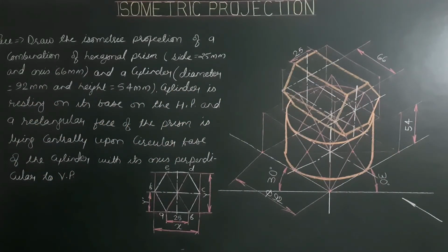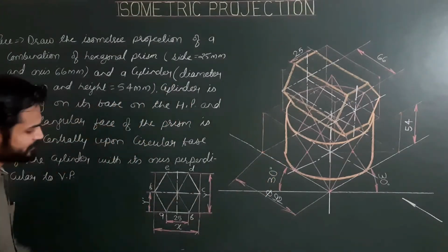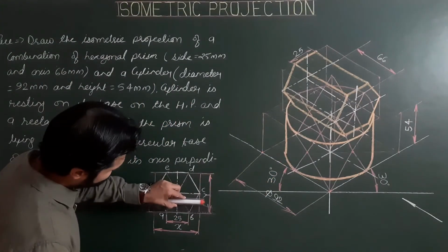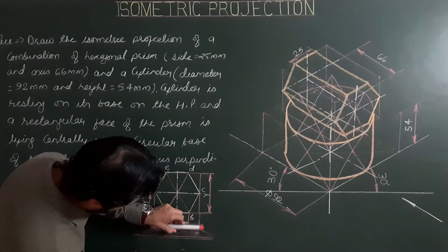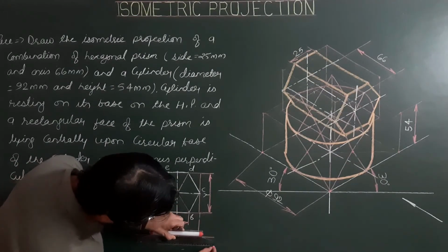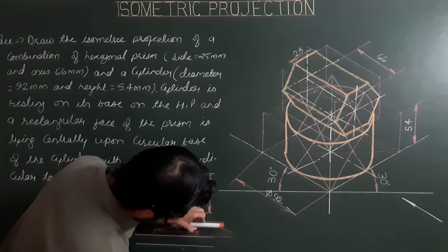And last, naming of the helping figure and final answer. So please write these headings in single stroke lettering, with letter height of 5, 8 or 10 mm.